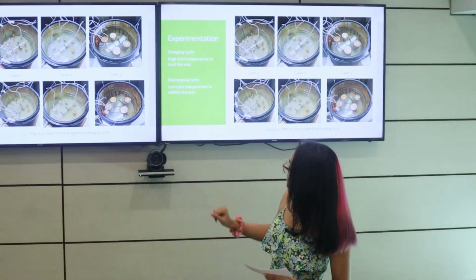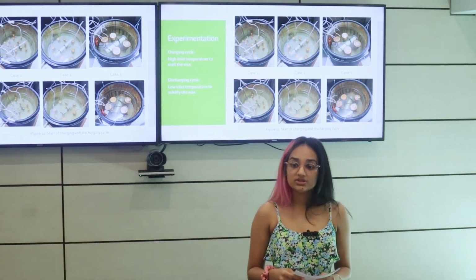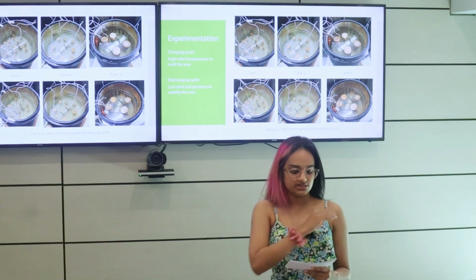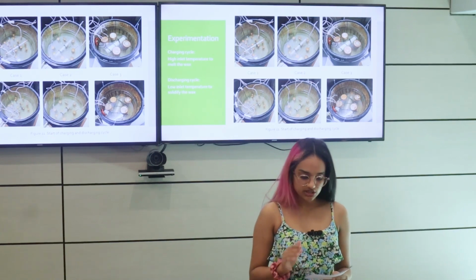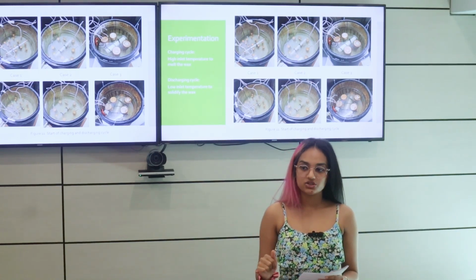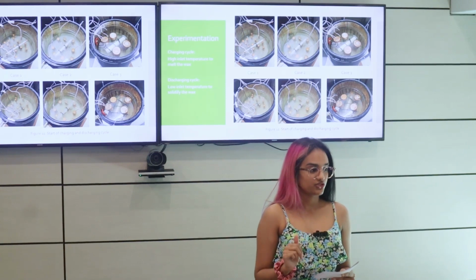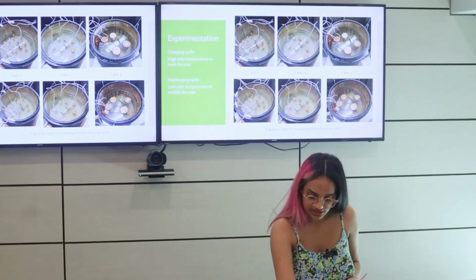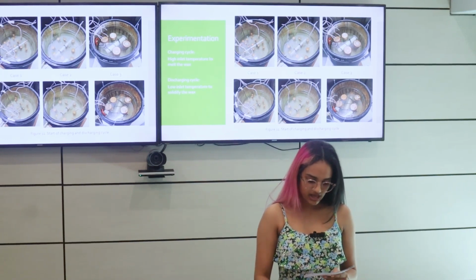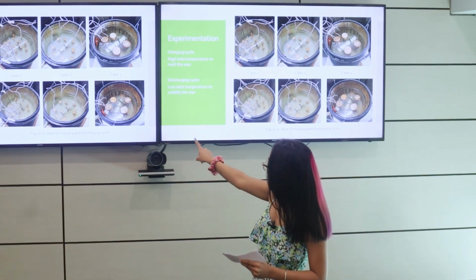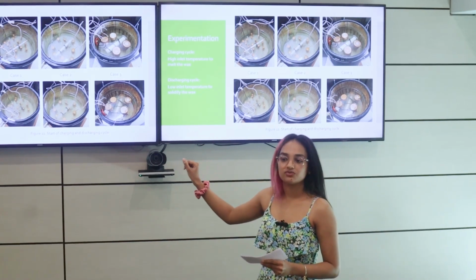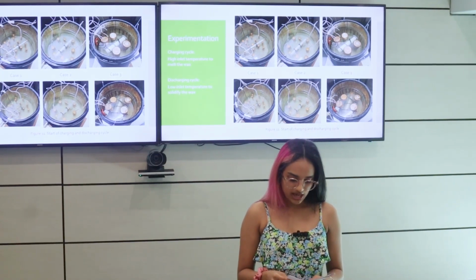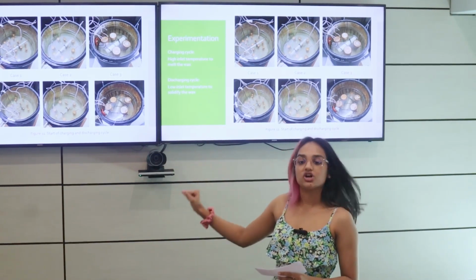The water preheater is switched on, enabling an inlet temperature to the vessel of 70 degrees Celsius. Heated water continues to run through the tank until the wax is completely melted and all temperature fluctuations stop. The fully melted wax can be seen in figure 11, the bottom row. Here you can see the opaque color, and according to the specifications of the wax, that's when it is fully melted. So it's not a clear wax when melted. When we see that, then the discharging cycle can begin.